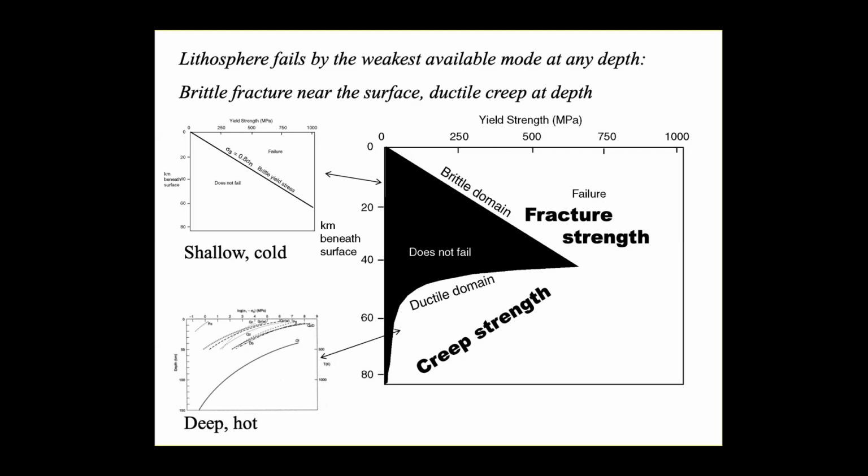But this conspiracy explanation was offered in ignorance of the understanding that rocks lose strength rapidly before they melt. And that applies to steel too. So we mentioned the homologous temperature, which is about 50% of the melting temperature. Up to the homologous temperature, the material has pretty much all of its strength.